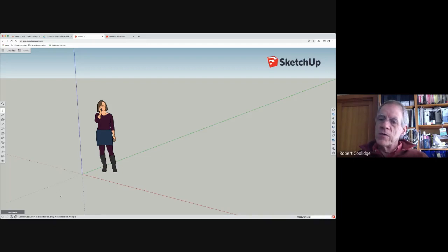So no matter what you pick as your template, if you pick feet and inches as a template, it assumes inches. So if you just type 30 return, it assumes inches. If you pick millimeters for your template, it assumes millimeters, so you can just write 300 return, and it'll be 300 millimeters.